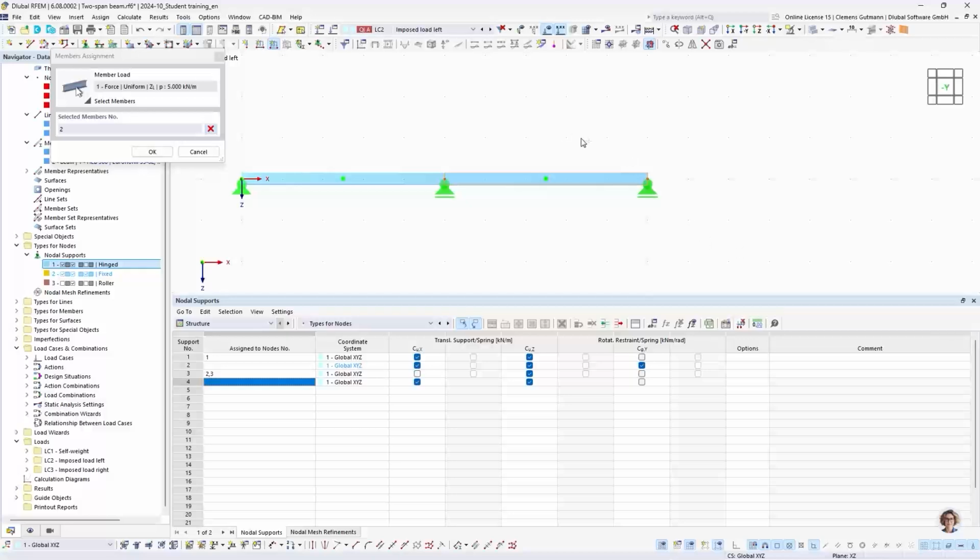If I do the same thing, sorry, deselect this. If I do the same thing by drawing right, it is not selected. So when the orange rectangle is used as selection, only objects that are fully inside that rectangle are selected. And if I do the same to the left and use the blue, also members that are only partly in that rectangle are being selected.